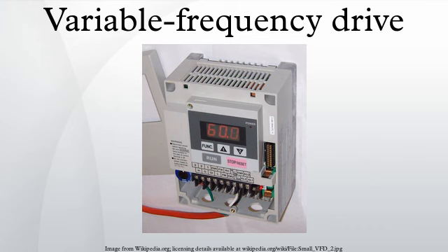Cycloconverter, Scherbius, matrix, CSI and LCI drives inherently allow return of energy from the load to the line, while voltage source inverters require an additional converter to return energy to the supply. Regeneration is only useful in VFDs where the value of the recovered energy is large compared to the extra cost of a regenerative system, and if the system requires frequent braking and starting. Regenerative VFDs are widely used where speed control of overhauling loads is required.